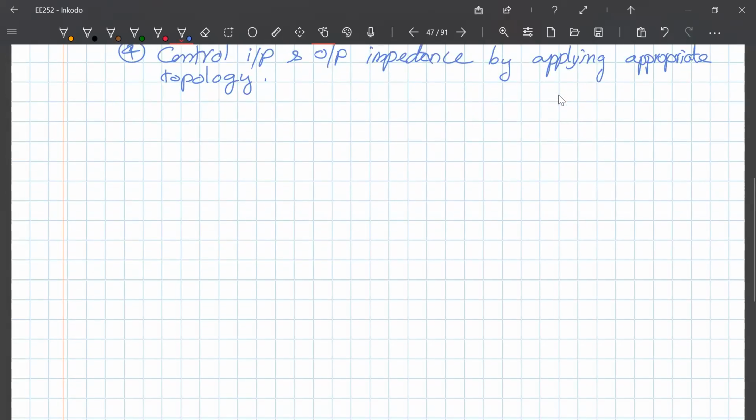This also extends bandwidth. Extended bandwidth means if I had a gain of 100 from, let's say, 10 hertz to 100 hertz, now I will have reduced gain, let's say amplification of 10, but now the range of frequencies that will have 10 will be maybe like 1 to 500 hertz, something like that. So an extended range of bandwidth.